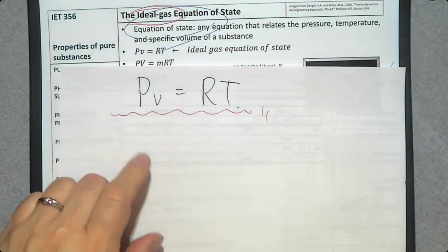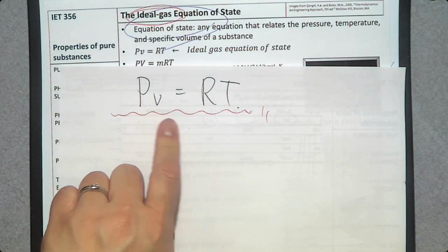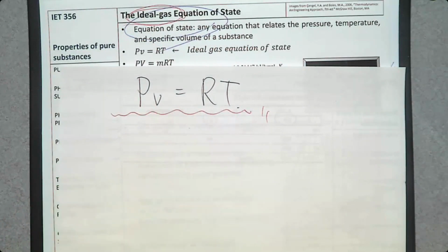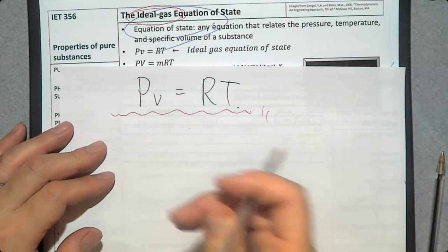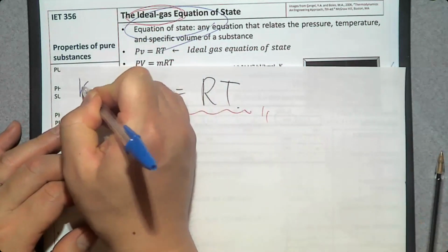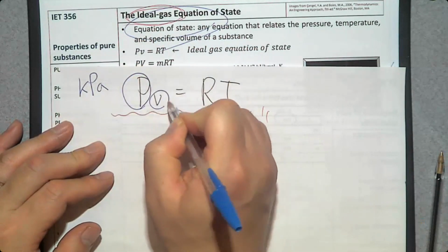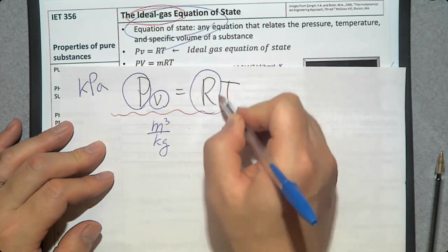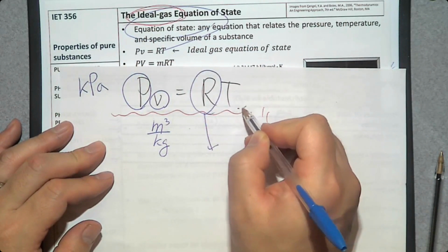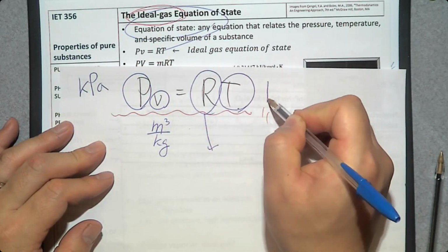Pressure has different units, and so do specific volume, gas constant and temperature. So let's talk about that. If you don't want to worry about any unit conversion in your equation, always stick to these units. For pressure, kilopascal. For specific volume, cubic meters per kilogram. For gas constant R, which we are going to talk about later, and temperature should be in Kelvin.